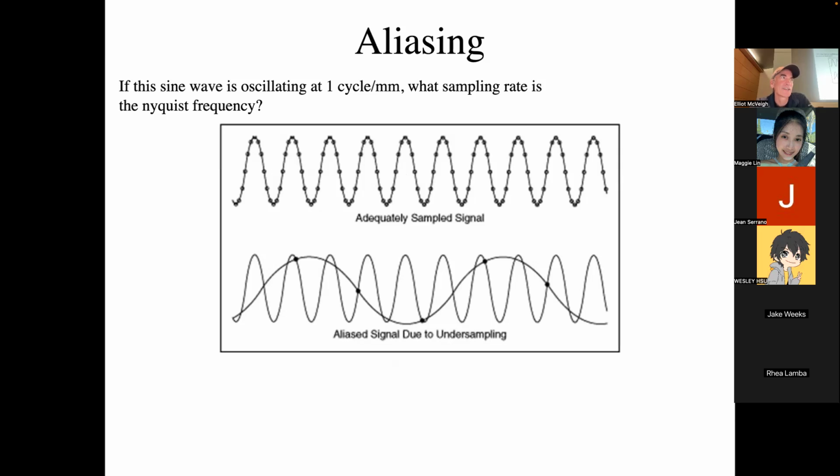And what's it aliased with? It's your high, say this is the limit, our band limit. For that sampling, that would be the band limit, right? We're getting 2 samples per cycle, right? But that band limit also corresponds to what's happening at the average, at DC, at 0 frequency, right?